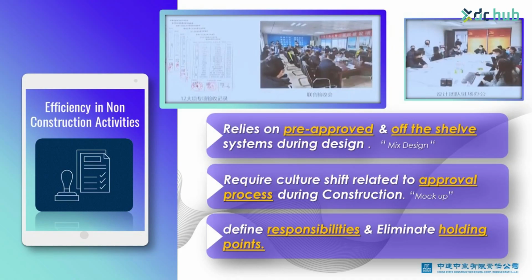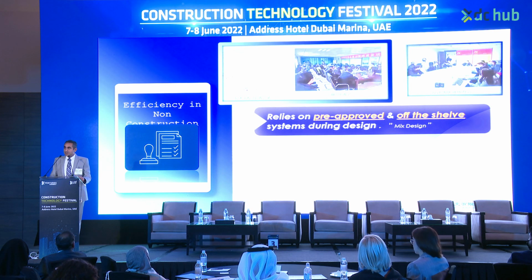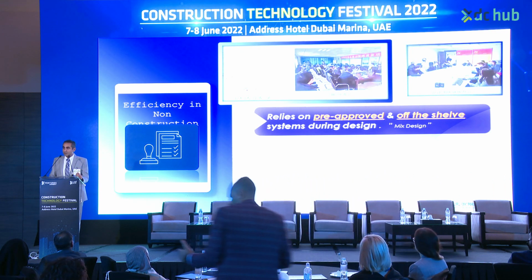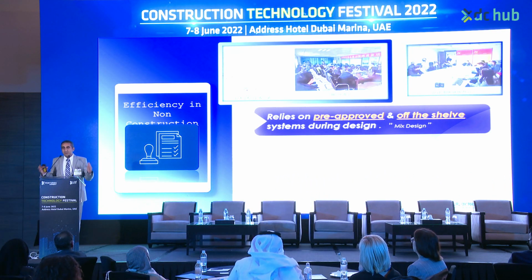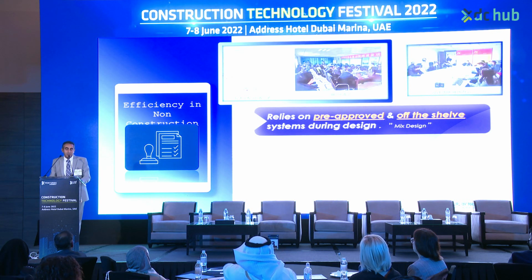We're supposed to know what we are doing because we have been doing this for so many years, and eventually in every project we go through the entire same process of design and design approval from the beginning. Imagine that every time we need to submit a mix design for concrete, and this mix design has to undergo testing, cube crushing, and we have to wait either 28 days or 56 days until we certify whether this mix design can be used or not.